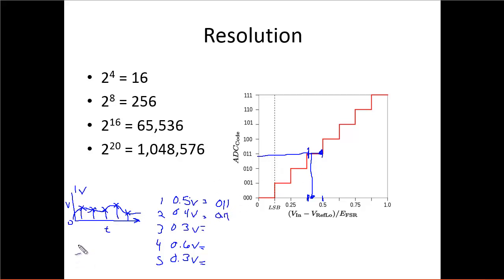So my readings coming out of the converter would probably look more like, say, this. Okay, so this is the result of quantization error, and as you can see, depending on how varied that step is, that's going to determine my amount of quantization error. So the more bits I choose, the more finely grained this is.